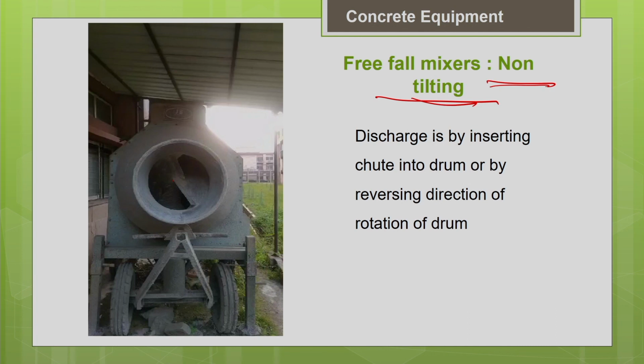Okay, so you can see there is another configuration where the drum is reversible. If you rotate the drum in one direction, it will facilitate the entry of the material into the drum. If you rotate the drum in the opposite direction, it will facilitate the discharge of material out of the drum. So, that is called reversible mixers. Reversible mixers are also available in the market.